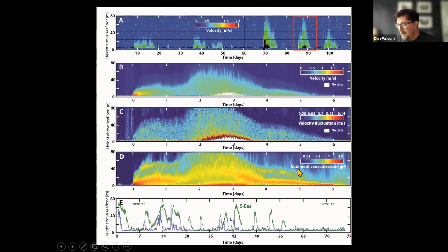And then we have suspended sediment concentration, which is recovered from the acoustic backscatter. So the way in which the sound is reflected back from the water column can tell you something about how much sediment it's carrying, and through an acoustic inversion technique we can have a really good estimate of the sediment concentrations within the flow, from a development that Steve Simmons in the team here in Hull has really been pioneering. However, in all of this, you can see that panel B is the velocity.